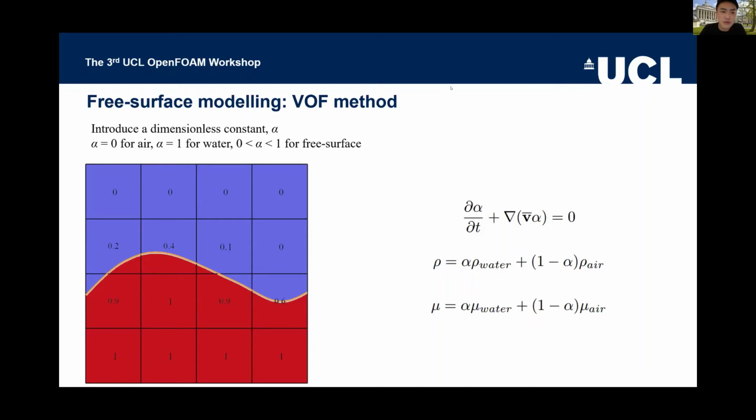So what we do here is we have the ship domain, and define it into 2 parts. This is water and this is air. When it's a static water surface, we shouldn't have any waves. But when we have a ship here, there will be some change, so there will be some cells with values of alpha between 0 and 1. How to set this? Okay, go to next slide.